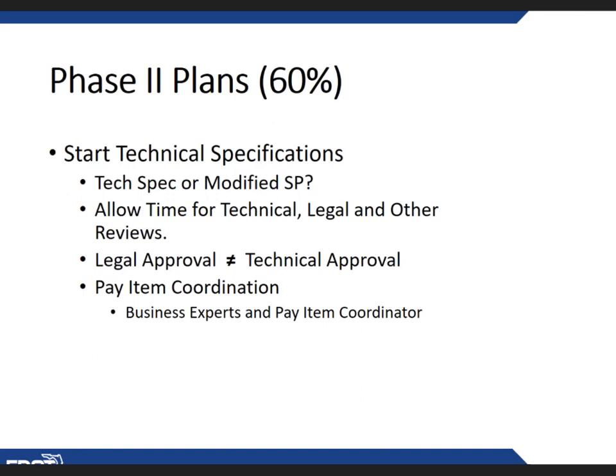I get a lot of questions on whether a plan detail will work instead of a tech spec. Well, it depends on how complete your plan detail is, but rarely does a plan detail cover the acceptance criteria, the method of measurement, and the basis of payment in a complete manner. So I think we'll talk a little bit more about this as we proceed, but just to be aware of it, those are some of the things we talk about with the basis of estimates training when we get into the pay items themselves in a little more detail.